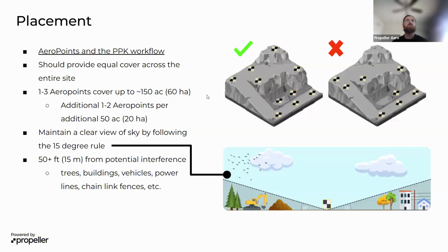So AeroPoint placement. If you can get AeroPoint placement dialed in on your projects, you'll have many successful flights and very few headaches, if any. So AeroPoints with the PPK workflow, we want equal coverage. So we want good distribution horizontally as well as vertically.